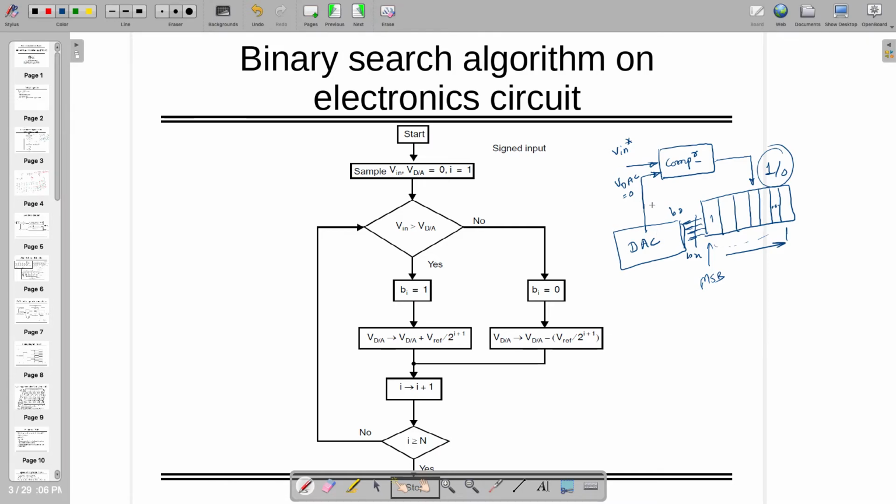And remember, in the DAC, although we have made so many capacitors, which you are also doing, there might be some extra parasitic capacitors. That will also create some problem. So you have to make sure that everything is 0. So you have to keep one extra switch in shunt with all the capacitors, right? So these are some tricks to design a DAC or ADC, right?